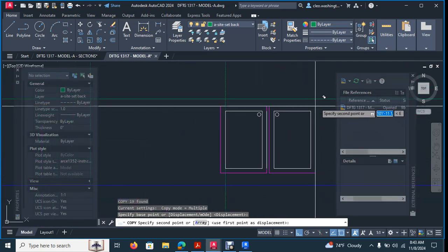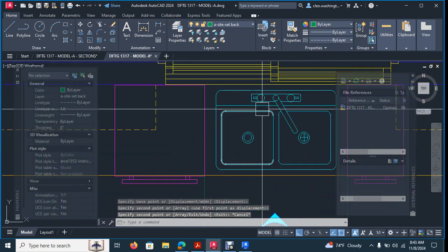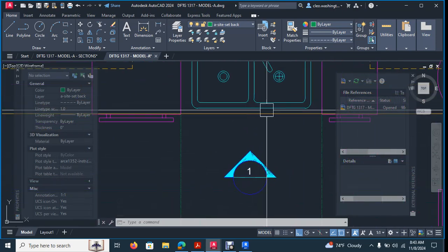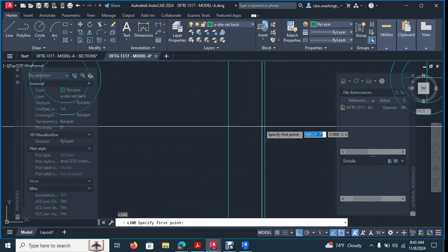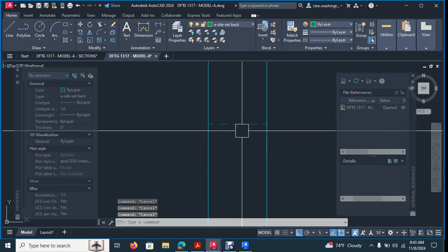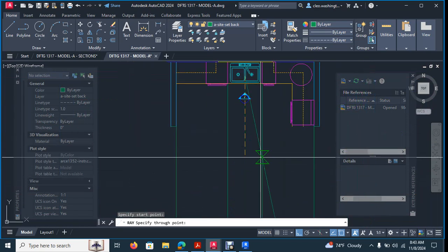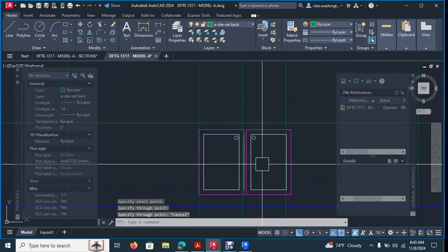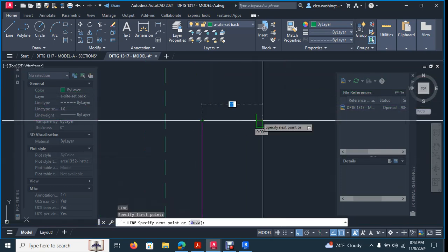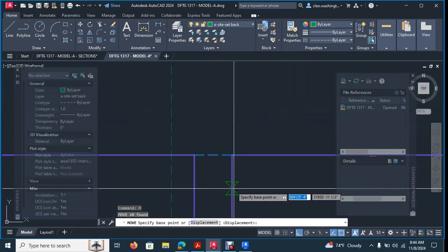So let's go ahead and drop these right here, and we'll have to make some adjustment because this kitchen sink and this millwork is a little bit smaller than the one we're copying over. So what we want to do is project a center line down. Draw that line right here, then trim it, and then type in Ray, and let's project that line down. Let's center this guy up on that line that we projected down. So now we go here, M for move.